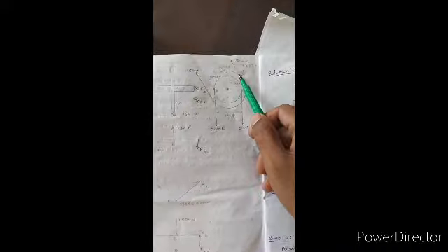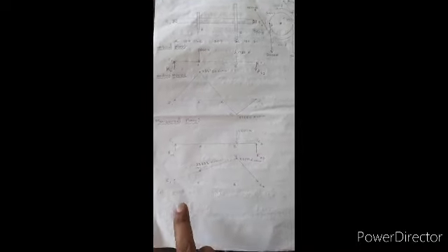If the force is acting only in the horizontal direction, then the bending moment diagram for the horizontal direction is enough. But here forces were acting in two directions. One more thing, here an inclined force is acting, so I am splitting it into vertical and horizontal components. Very simple, but you have to practice it, and you should have basic knowledge about bending moment diagrams so that you can easily solve this problem.